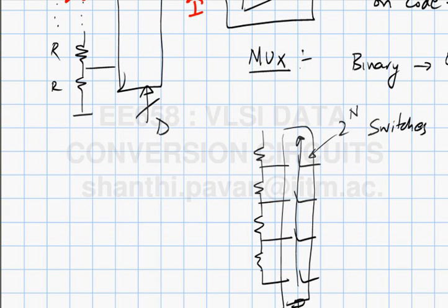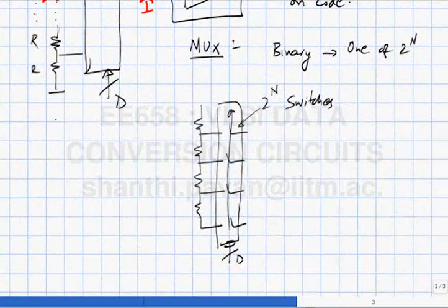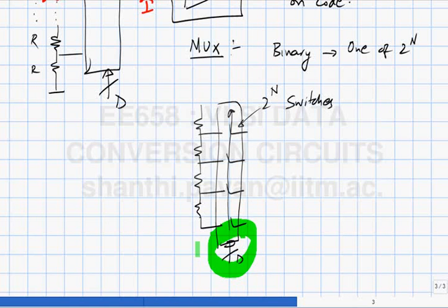The advantage with this... is this the only way to do the mux? You can use a tree, right? So you select either the bottom half or the top half, and then the bottom half or the top half of those sections, and so on. So this can be a tree type mux. That will basically simplify the decoding, which here is actually a pretty complex process.